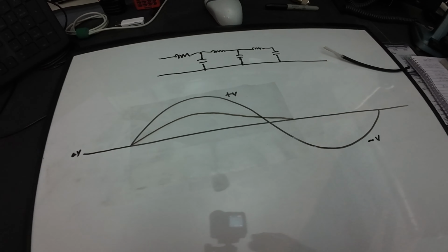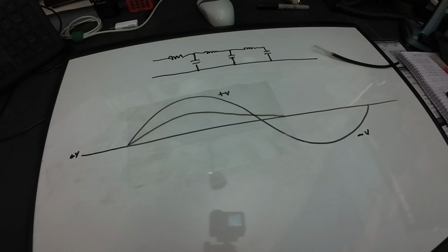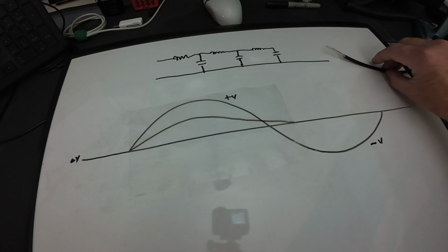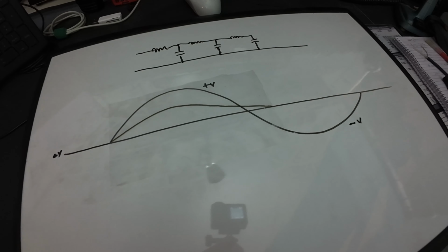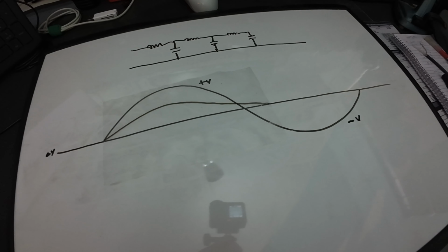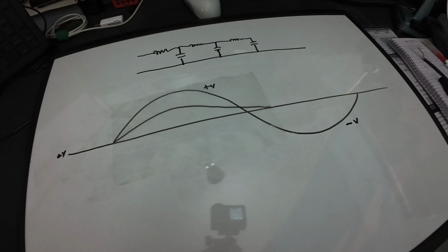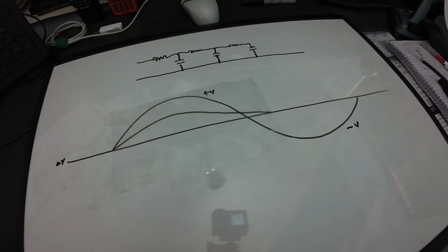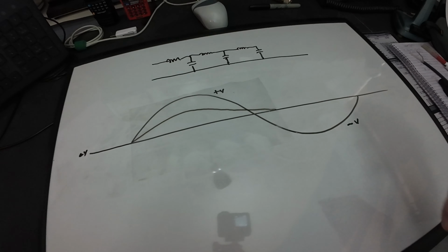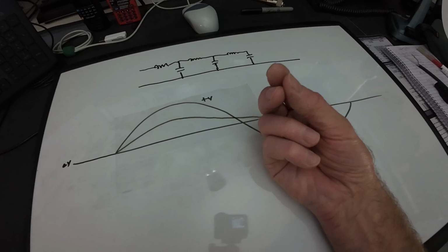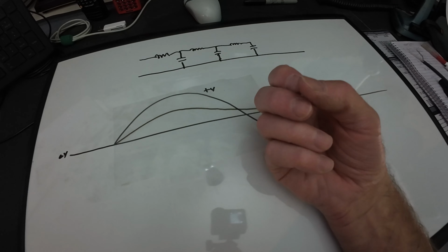One of the first places I noticed this aspect of RF was when taking apart SWR meters and watt meters and taking a peek inside those devices, or even radios. If you look inside, what you'll typically see is a little flat disc capacitor right on the SO239, soldered to ground.